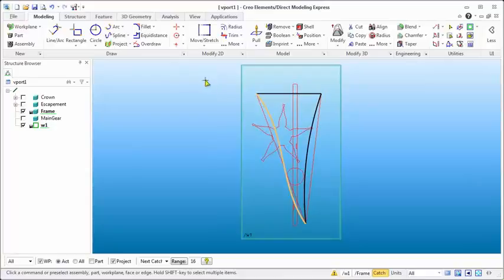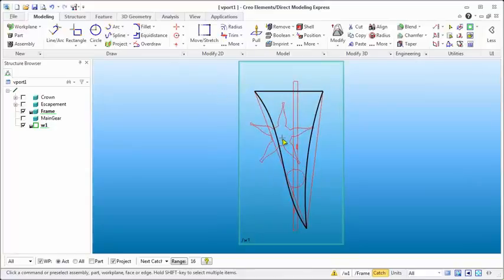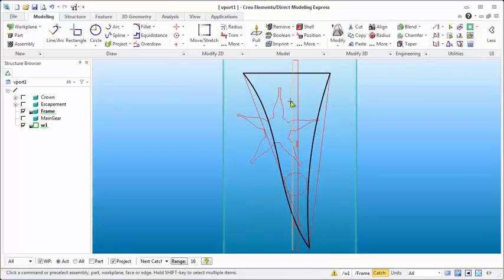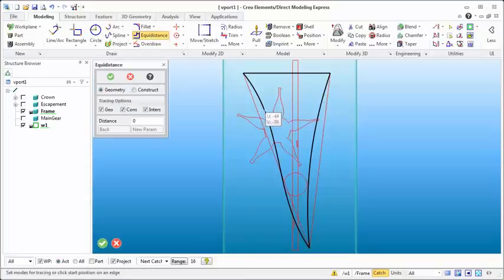Now, one of the things I want to do is also have this be a little bit hollow, so you can see all the gears and the mechanism and how everything works within the clock. So what I want to do is make an equidistant contour offset. Now this is one of those things where it gets kind of interesting because this isn't a very intuitive command. Right here as it is, it's not really letting me select any geometry. If I hold down shift though, however, it will.